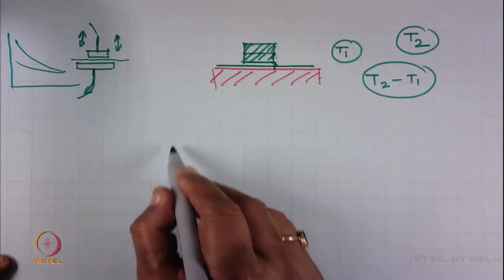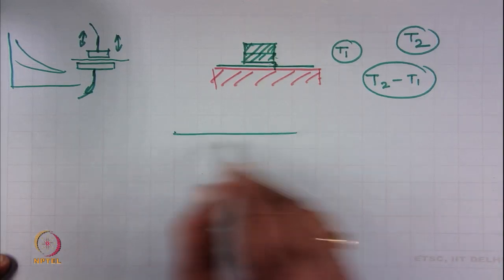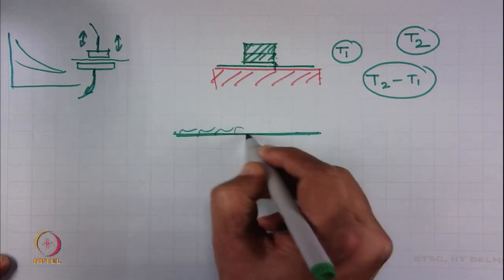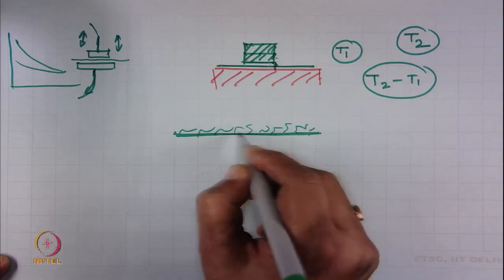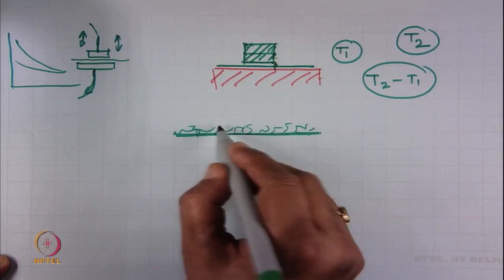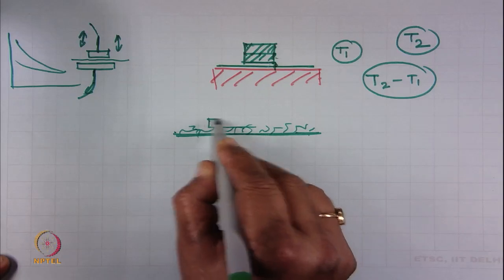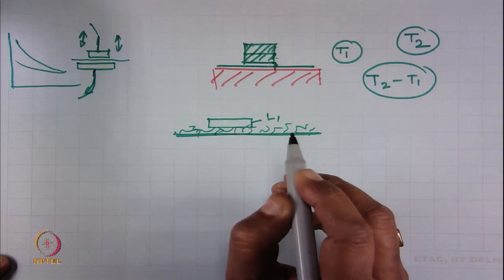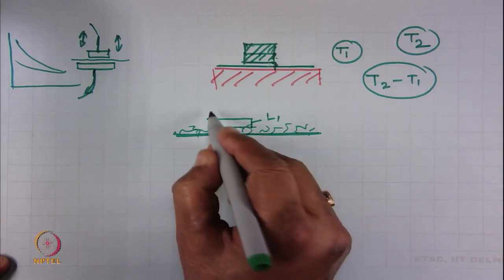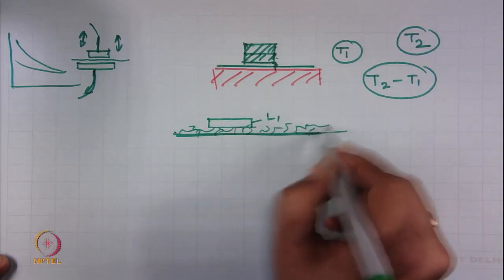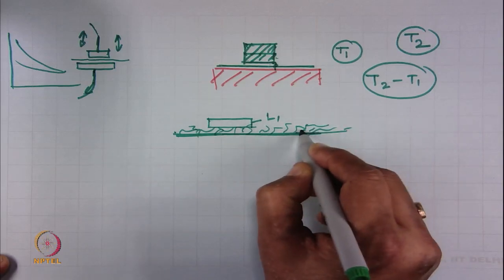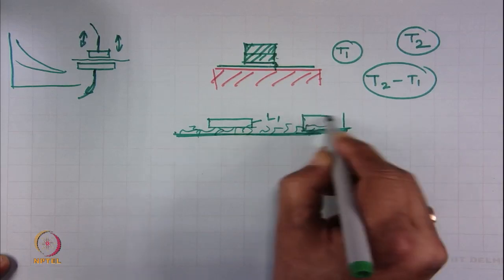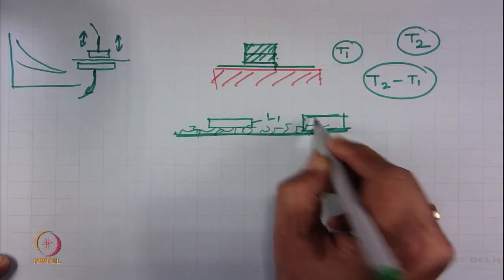What is surface thickness? Suppose this is a fabric, and it has some hairiness on the surface. Initially, at a lower load, load 1, we measure the thickness. Once we increase the load, mainly these hairs will get compressed.